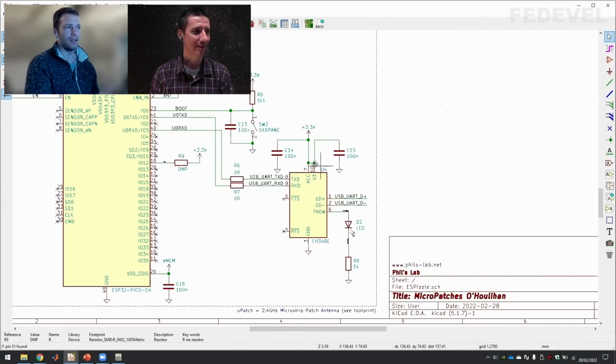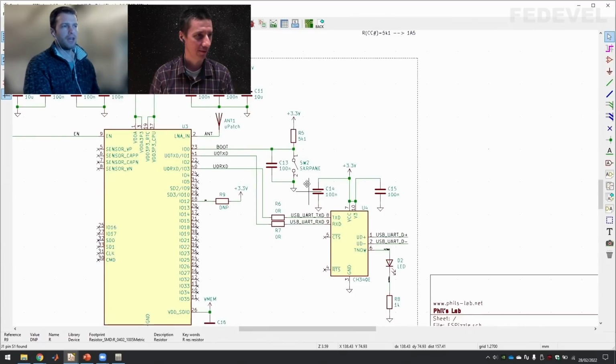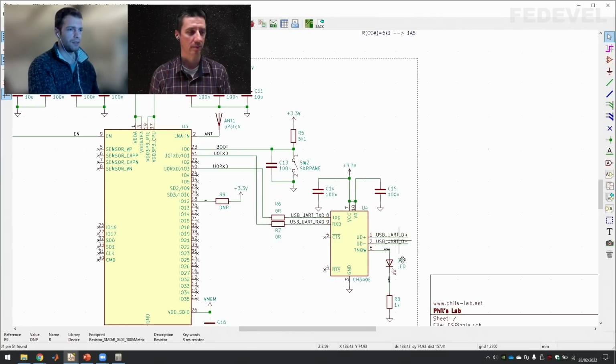How do you program or debug this microcontroller? So it has JTAG as well, which I haven't exposed in this case. I didn't feel like getting a specific JTAG probe for this just yet, and I don't have a Segger one, which I believe could debug this. So it's all via UART. You can change the boot mode to essentially flash the program. There is a bootloader or something? Yes. Okay. And that works via this USB UART connection.